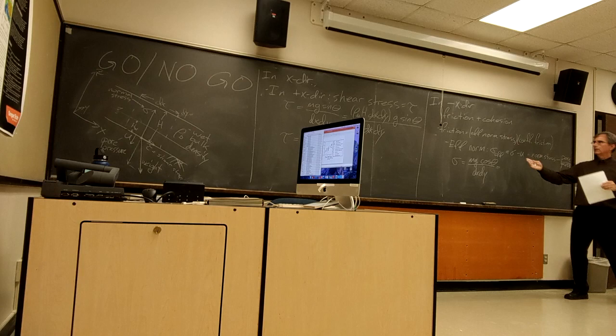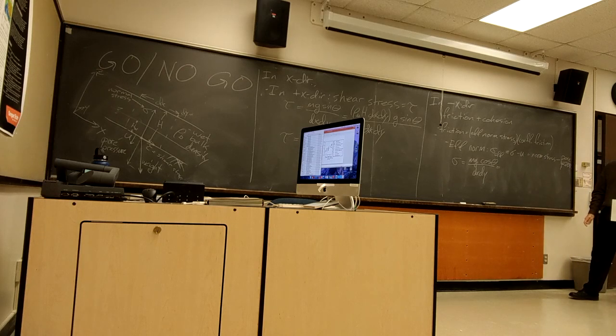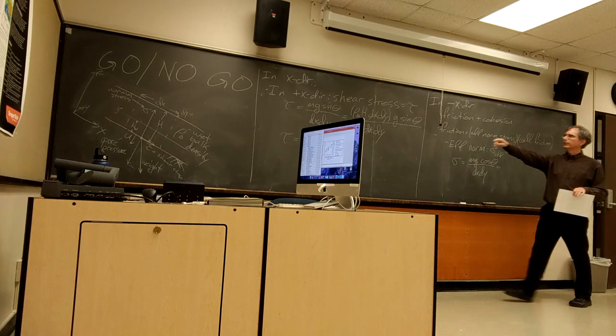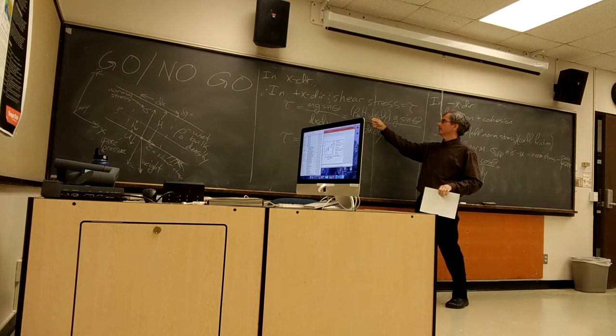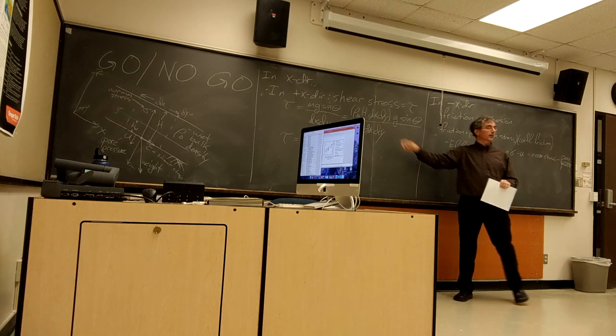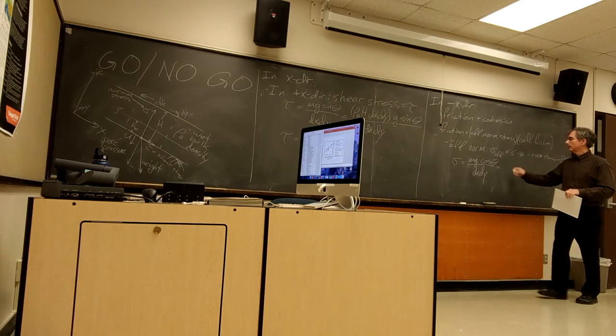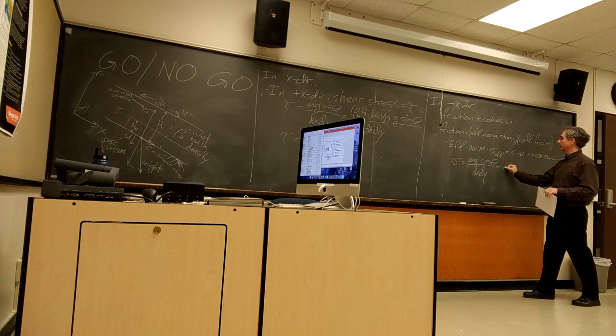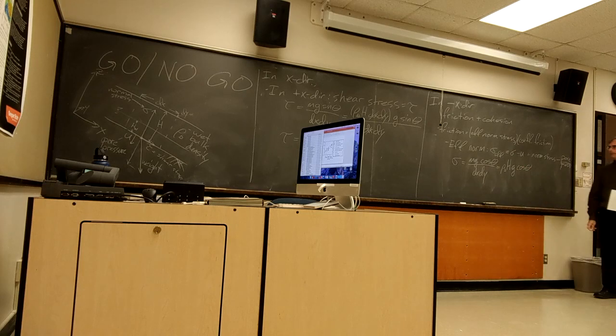And if you'll allow me to skip the belaboring step of writing up the rho b times h times dx dy, canceling out the dx's and dy's, then I can simply write that my normal stress is the wet bulk density times the soil thickness times gravity times cosine of the slope angle.